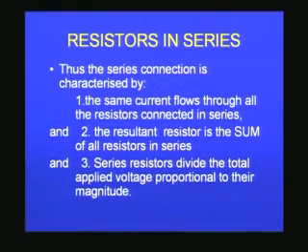These are the two important points that we should always keep in mind. Thus I have summarized here, the series connection is characterized by, 1, the same current flows through all the resistors connected in series. 2, the resultant resistance is the sum of all the resistances connected in series, and lastly, series resistors divide the total applied voltage proportional to their magnitude.